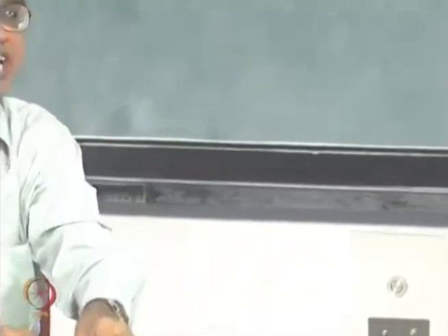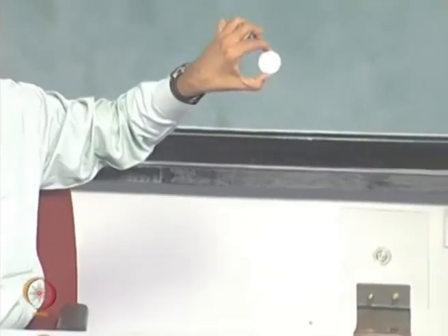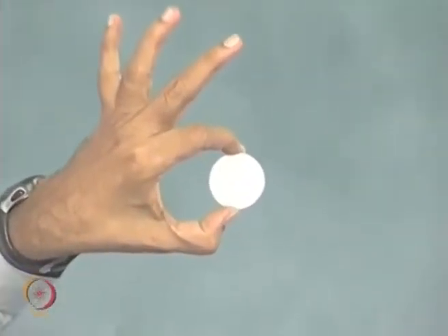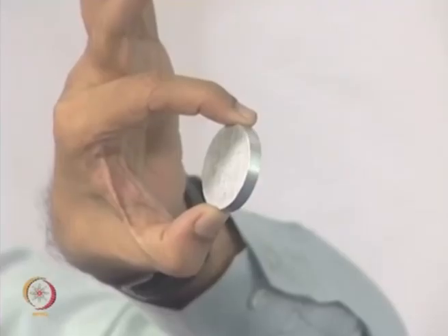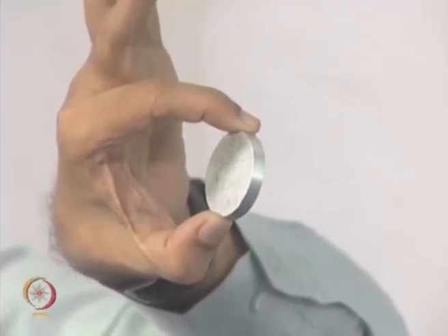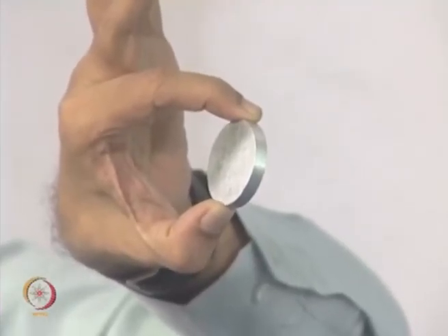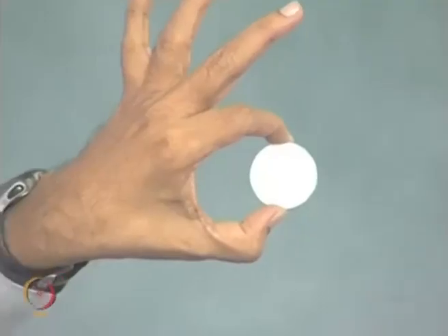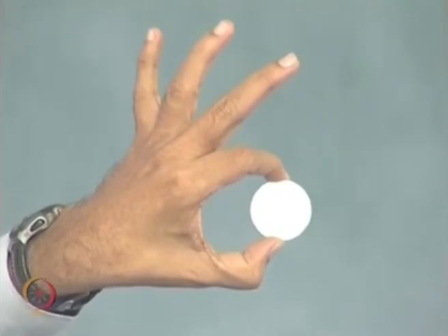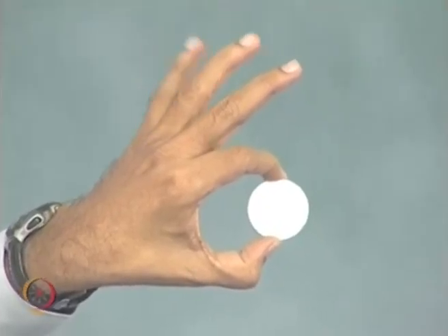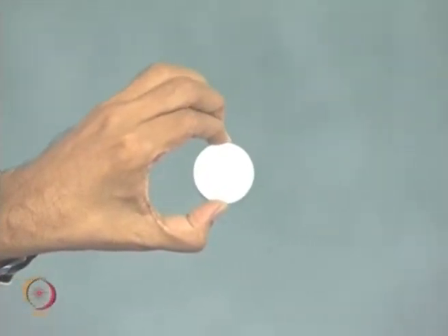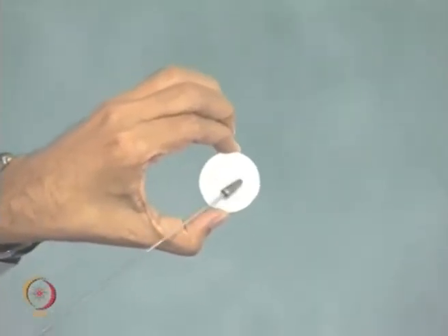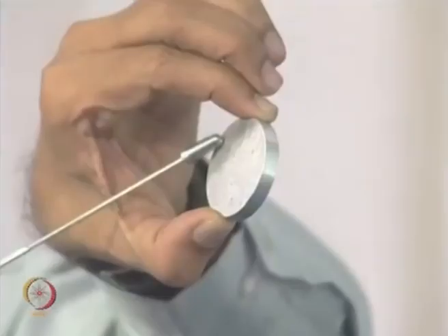Suppose I change the shape to a circle and I put compression, and this is the most celebrated model that you use in photoelasticity. You do not have a solution from strength of materials, but you can definitely find out a closed form solution from theory of elasticity. I can use Boussinesq solution and get the stress field at every point in the model.